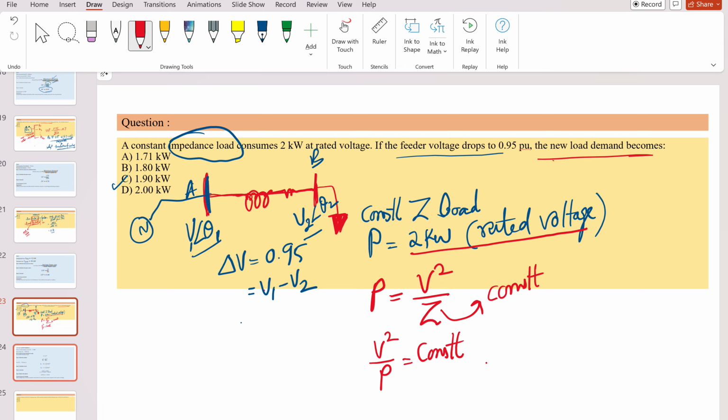So we are considering continuous reactance and not lumped, if I'm not wrong. Lumped is basically considering the summation of all the reactances. If I am considering that less current is being drawn in between, you can lump those continuous reactances into a single system. That is considered a lumped system. The drop will be the same, with only minute changes of 0.001, 0.05, 0.06, if not much current is drawn in between.